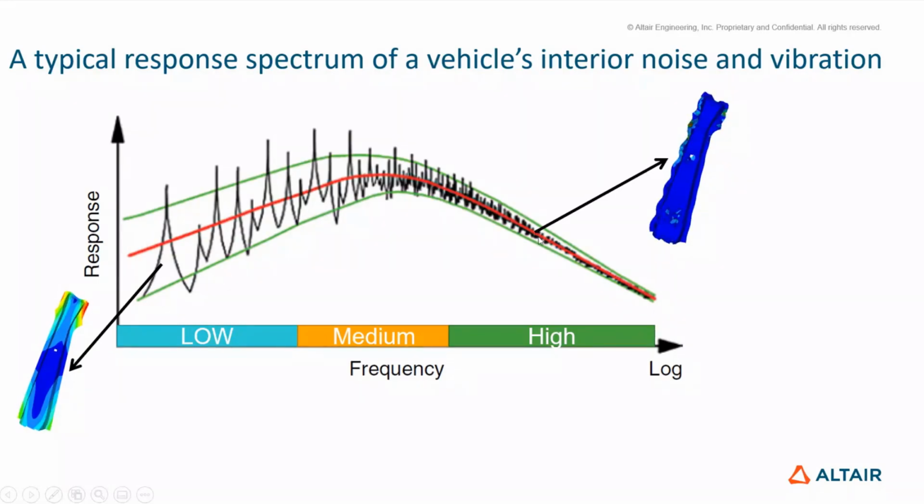On top of it, you have manufacturing changes, and even small changes at higher frequencies will change the mode effects. Whereas low frequency FE solvers are very good in helping you solve a particular peak using different diagnostic methods, in high frequencies that is not possible because the peaks are very closely placed together.